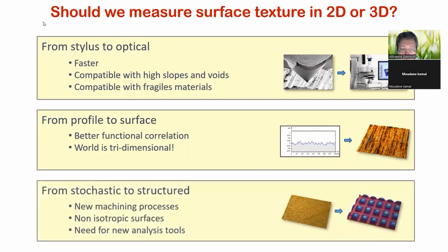Thirdly, industrial surfaces nowadays are often structured or textured to imprint a special texture that performs the desired function. For example, hydrophobic surfaces are often equipped with microscale geometrical structures such as pillars or pyramids to prevent droplets from adhering. They require new analysis tools and require aerial measurements. These 3 reasons explain why surface metrology has changed so much in recent years and that new analytical tools and new measuring instruments have appeared.